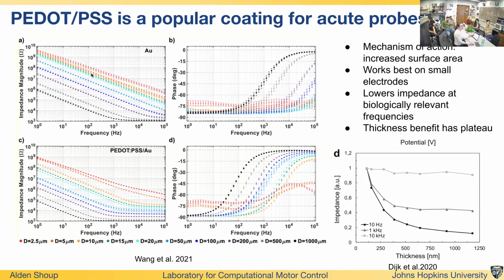about the electrode. So the impedance magnitude, we relate to the resistance of the contact. And you can say, okay, you want more charge to pass through your electrode, so you want your impedance to be lower, essentially a lower resistance. And then with phase, a perfect capacitor has a negative 90 degrees phase. And so we want to carry a lot of charge. We want our electrodes to have high capacitance. And so the more negative your phase is, the better your electrode is as well.